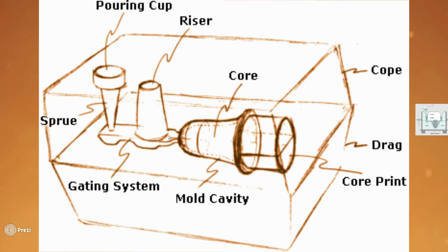You can see something different from the diagram that I showed you before, too: this riser actually comes in front of going to the core, whereas before the riser was afterwards. So you can put it in front or afterwards. Sometimes there are risers before and afterwards. It's however you want to do it. Then here you have, of course, your mold cavity. Here they have another core holding that open space because you don't want metal to fill that. Okay.